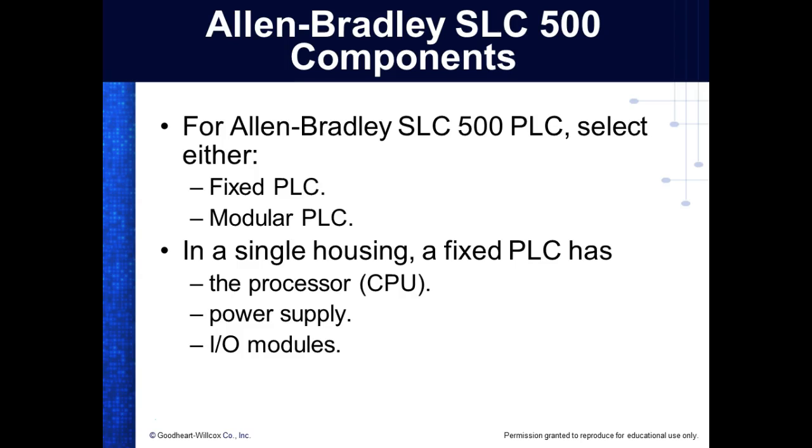Cheaper to maintain. It's just like power. You see Alabama Power send 3-phase. They could build a 3-phase transformer, but a lot of times they'll use 3 transformers. Yeah, single phase, but they hook them up for 3-phase. Why do they do that? Well, it costs them more to invest in it, but it's cheaper to maintain. And over time, you have to change the 3-phase transformer out. So you save money over time. Those transformers always go. You ever see one blow up? Especially the big ones.